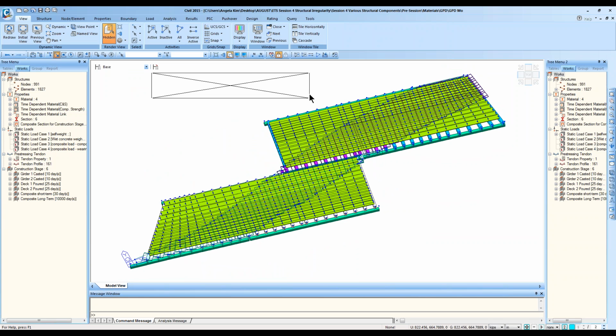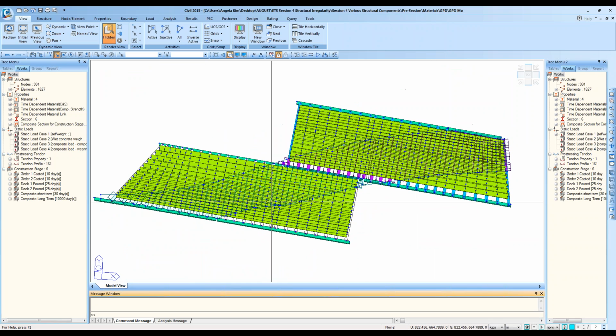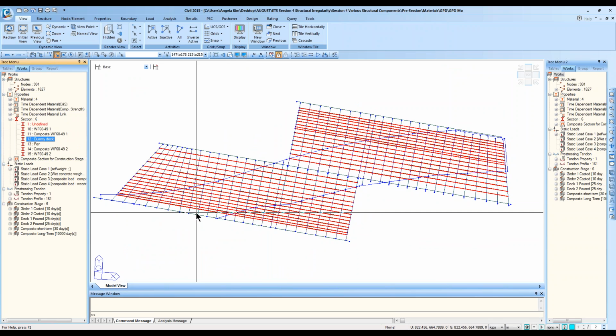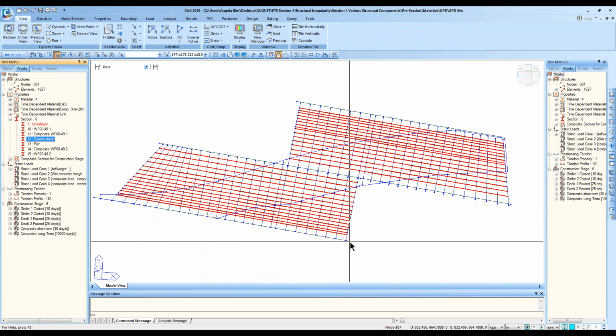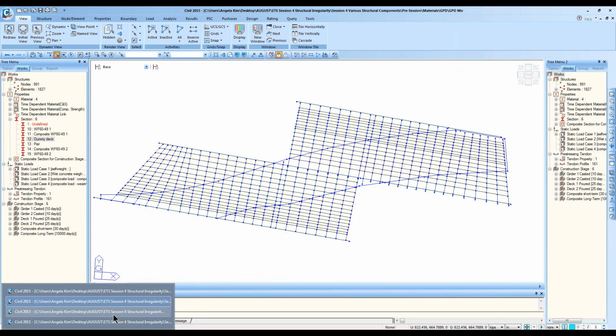Right now, what you are seeing are these green beams that are representing the deck in the transverse direction. They are indeed the dummy deck members, and they lie in the transverse direction of the girder in order to provide a transverse stiffness of the deck, which isn't provided by the longitudinal members. And for this one too, I imported from the CAD.